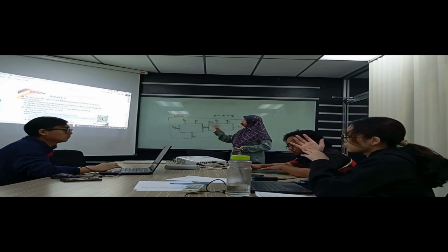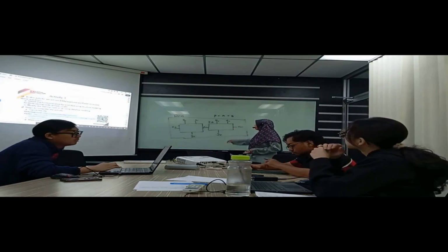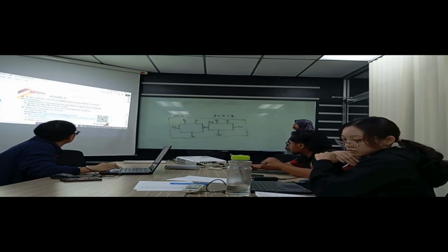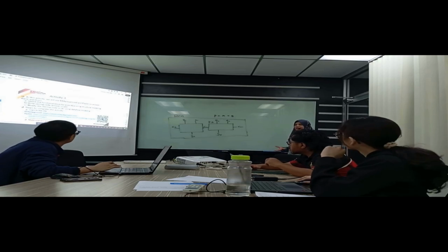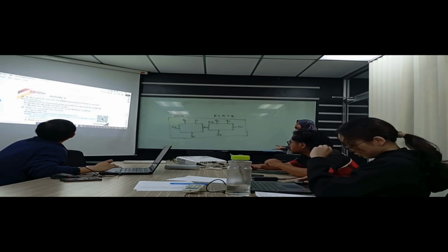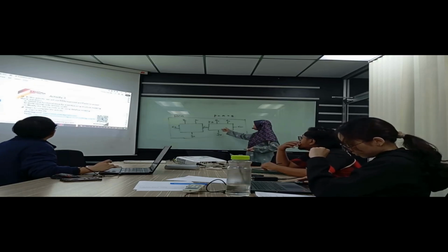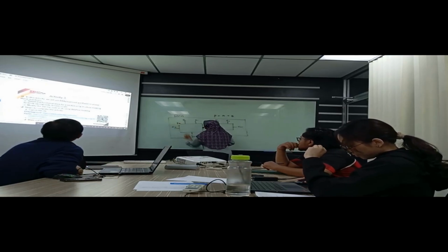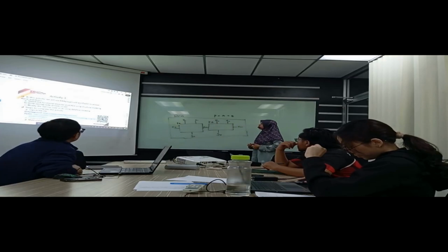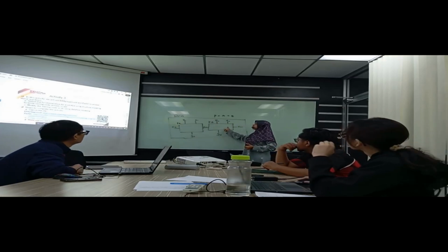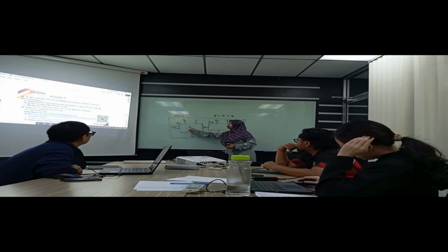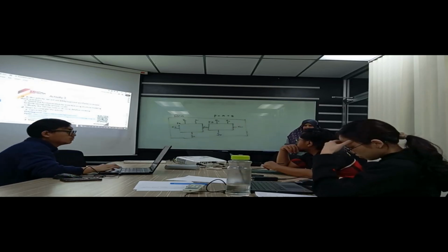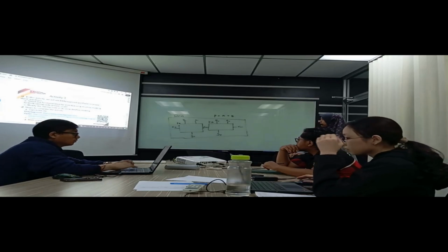Then you need to write the code for this using structural modeling. It means you have to call the block named FA 4 times. You need to instantiate this module FA 4 times. Can you do that? And then share it in the Padlet.